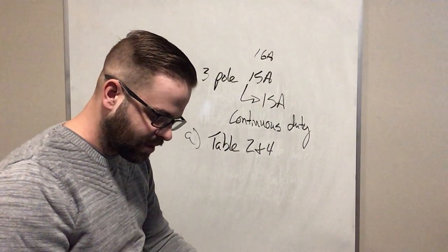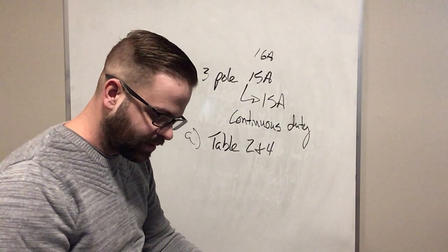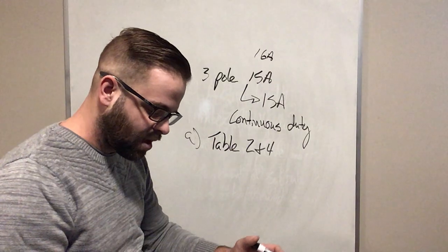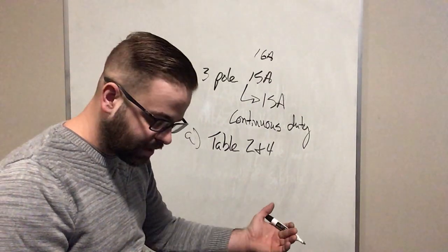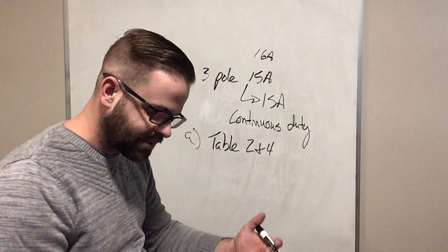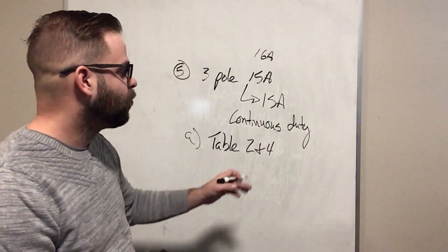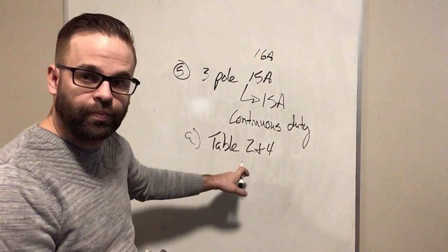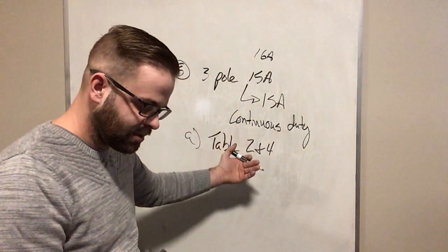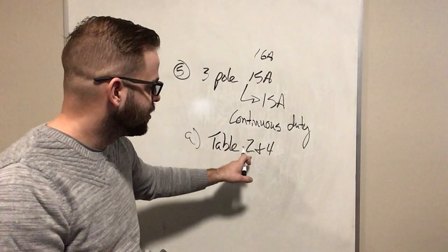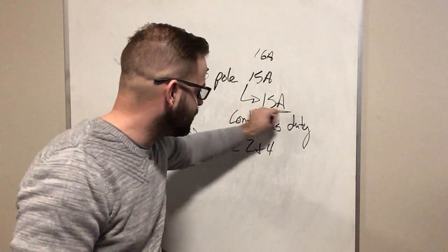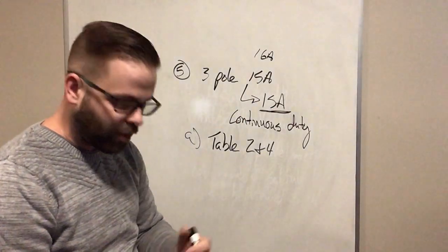So the continuous load as determined from the calculated load. So our calculated load cannot exceed the breaker size and shall not exceed 100%. So when we go to calculate out the breaker size and the wire size, neither shall exceed the set breaker size. So I can go up to 100%.